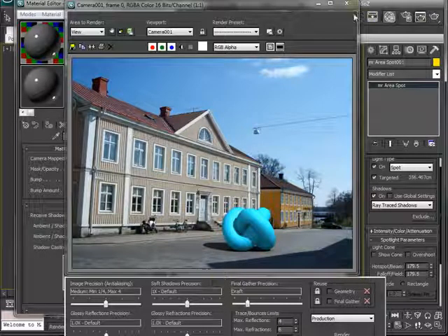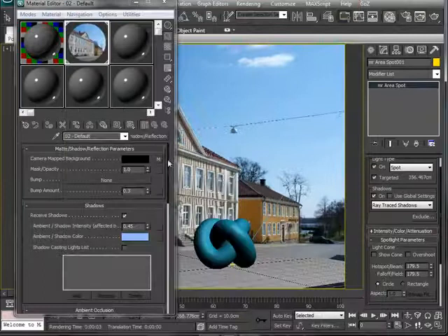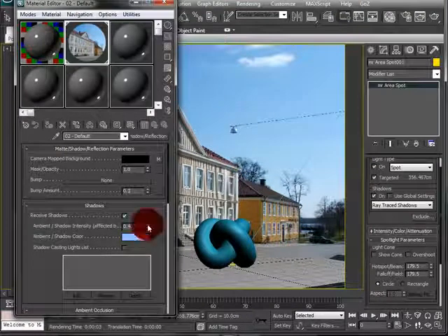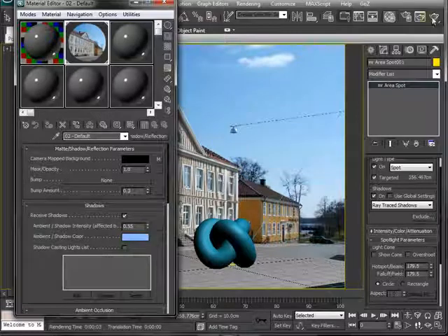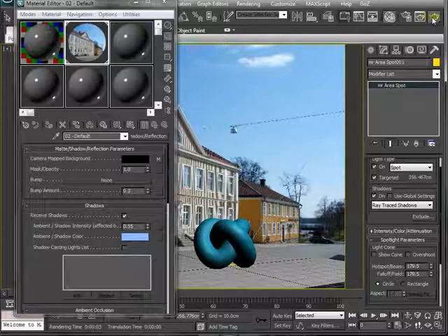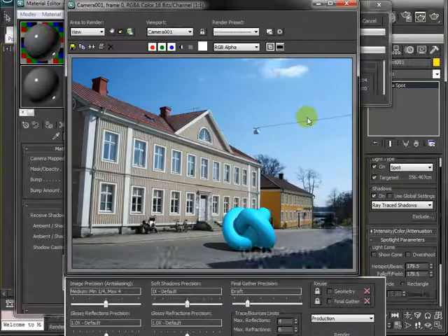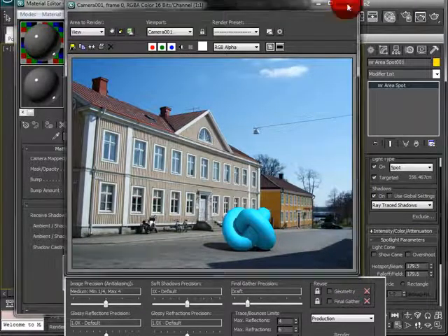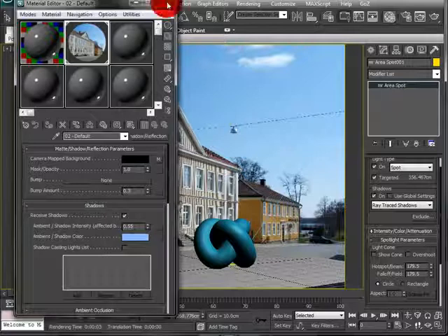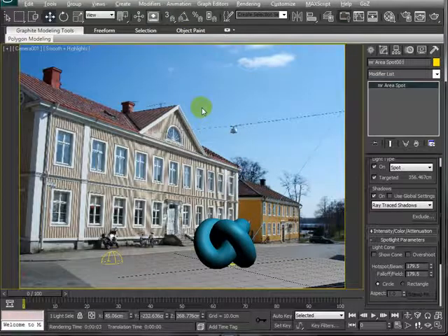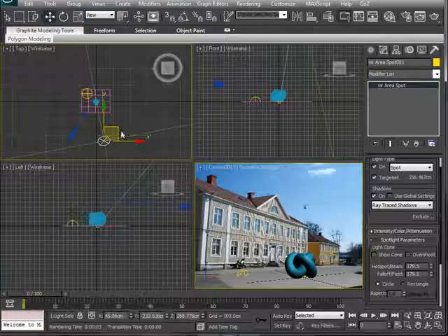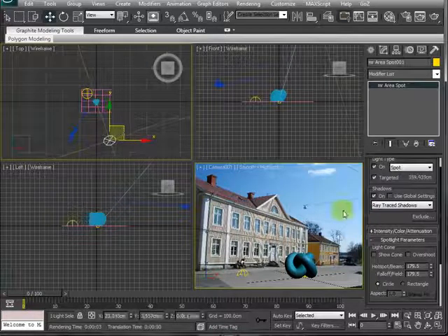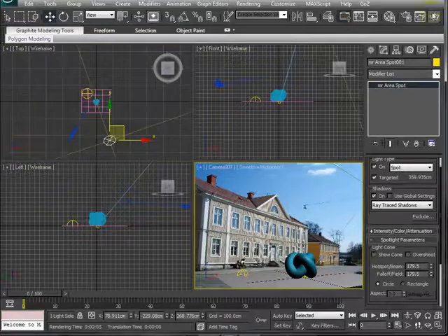Because I've changed the colour, it has become a bit more opaque, so I've introduced a darker colour. So just pump this back up, maybe to 0.55, and re-render. Excellent, that's a pretty close match now. I might just alter the position of the light to get a slightly more angled shadow, because it might not be entirely realistic to the scene, but I think your eye will accept it better if you've got a bit more angle on that light.